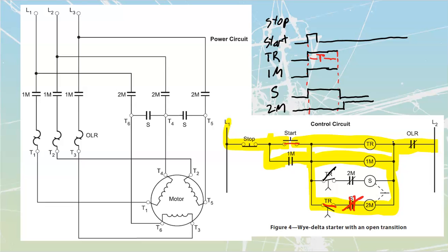So now we can carry the rest of these lines out along here, and then the very last thing that we'd have to look at is what happens when we press our stop. We'll take the stop over here, we'll drop on the stop. When we drop on the stop, it is going to interrupt current flow to TR, interrupt current flow to 1M, and interrupt current flow to 2M. So we're basically going to see, as soon as we apply the stop, that the entire circuit over here, anything that's high, is just going to go back to being low. That one's going to drop, that one's going to...